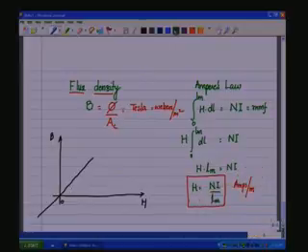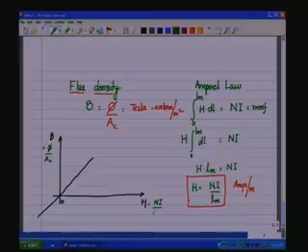This axis is flux per unit area. This is MMF Ni by path length, amps per meter. This is Tesla or Webers per meter square. Now this slope here, delta B by delta H, is mu.